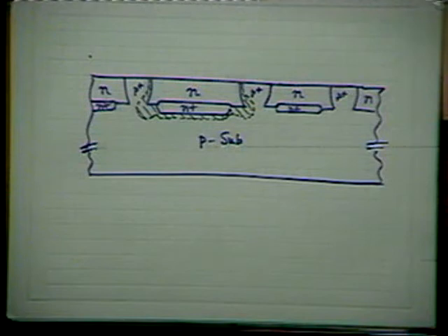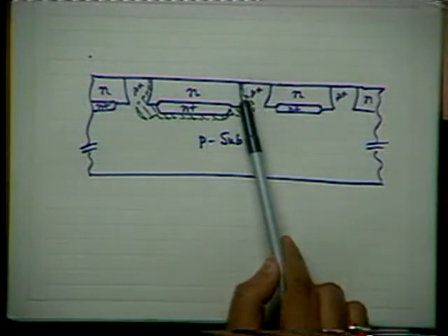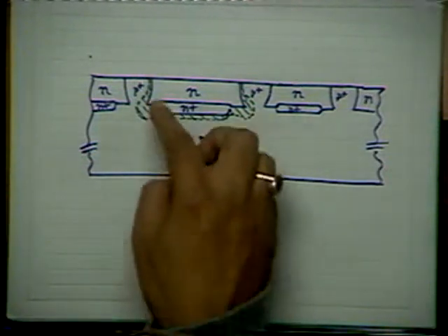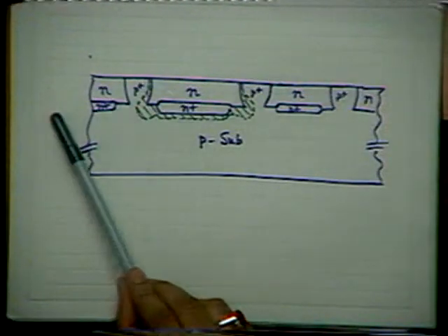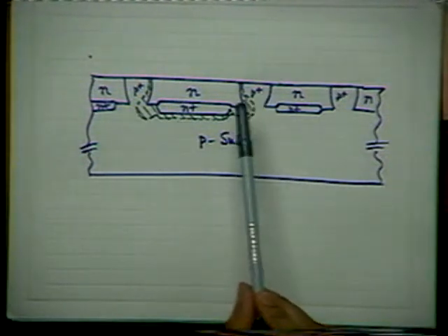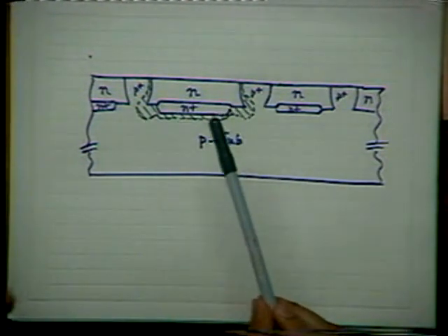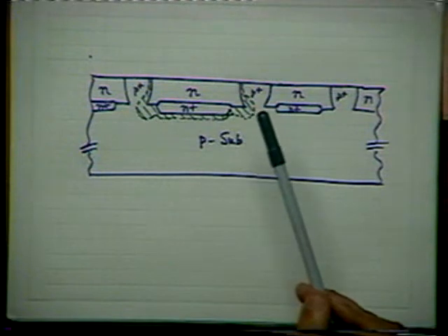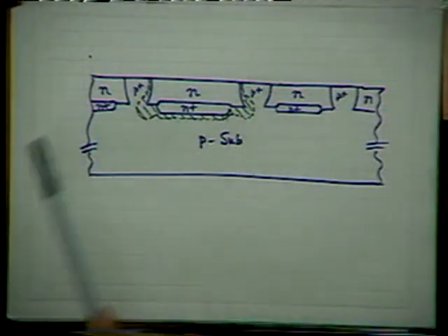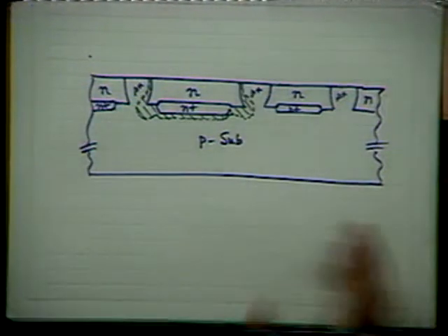Structurally we can divide the capacitance around an island into two: the capacitance of the sidewalls and the capacitance of the bottom. It can be shown that it is the sidewall component of the capacitance which plays a very important role in electrostatic coupling between the islands, to produce the so-called electrostatic leakage, capacitive leakage. By electrostatic I mean capacitive leakage. Because the capacitance of the diffusion sidewalls will be much more than the capacitance of the bottom portion.